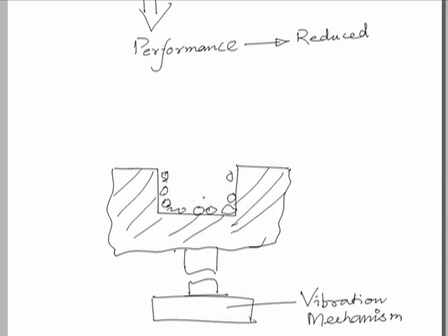So, if this is vibrating, then this will also be kept on vibrating because of the workpiece. So, this will hit the abrasive particles and keep them vibrating in the machining zone instead of getting clogged here inside this, and the effectiveness of these abrasive particles will increase in this way. And since this will be kept on moving, there will be possibility for new abrasives to enter into this zone and the continuation of this machining process.